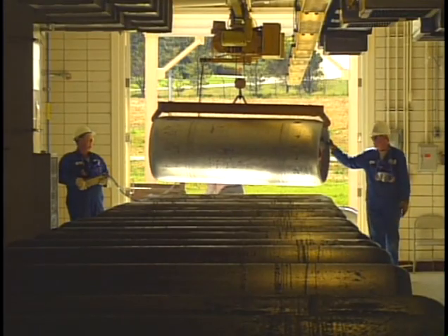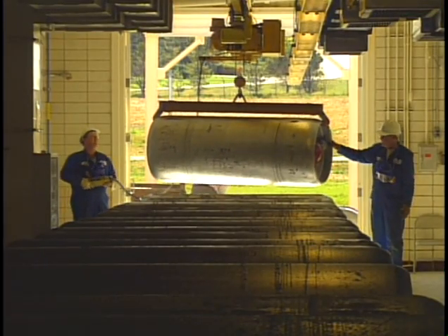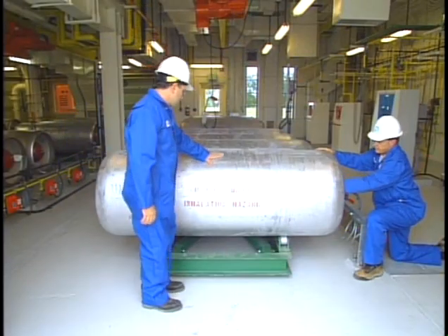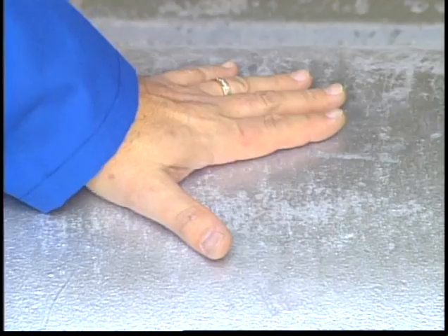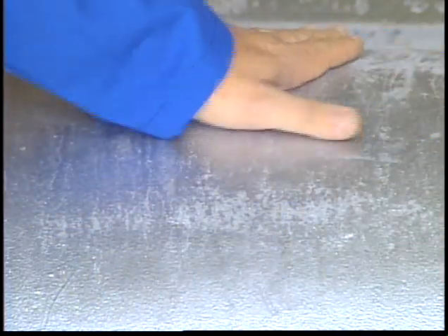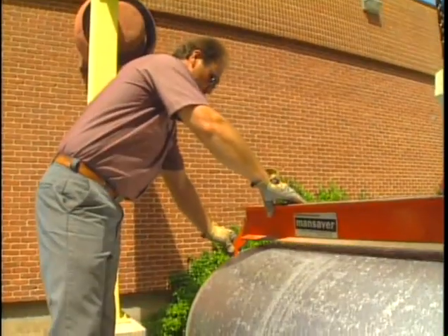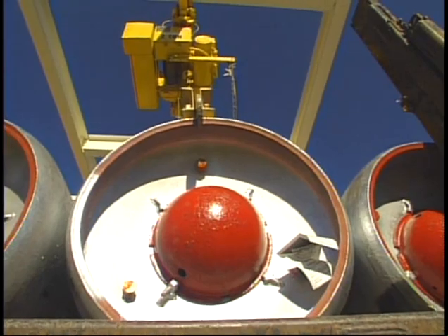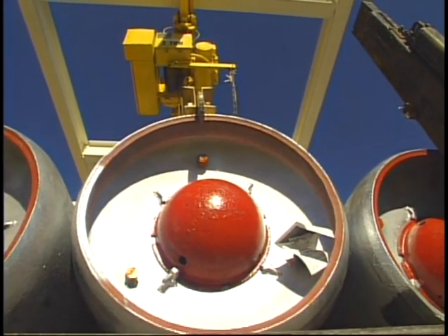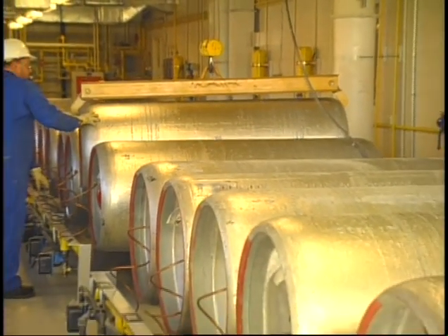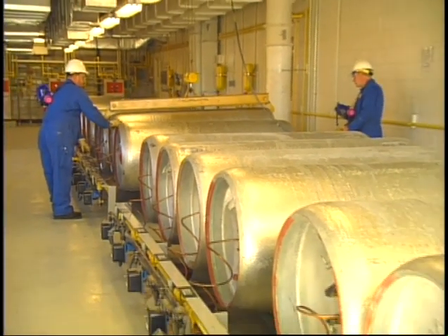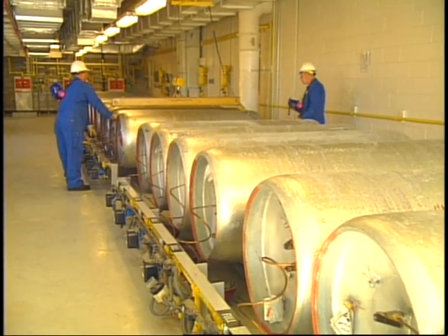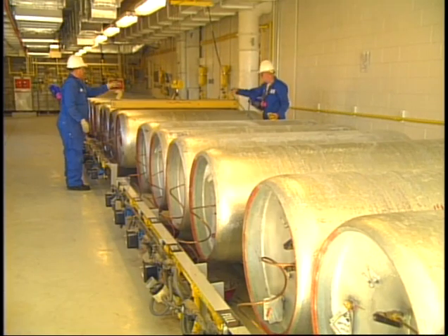Chlorine cylinders can be damaged during transport, so before you accept them, visually inspect the entire cylinder. Check for gouges, dents, pitting, bulges, and corrosion. Also feel them to make sure they're cool to the touch. A hot container may be contaminated. Attach them to the hoist carefully, always making sure the valve covers remain in place and are not attached to any of the rigging. Once downloaded, block the cylinder and use extra care when removing the rigging to avoid contact with the valve and any of the chlorine lines in the vicinity.